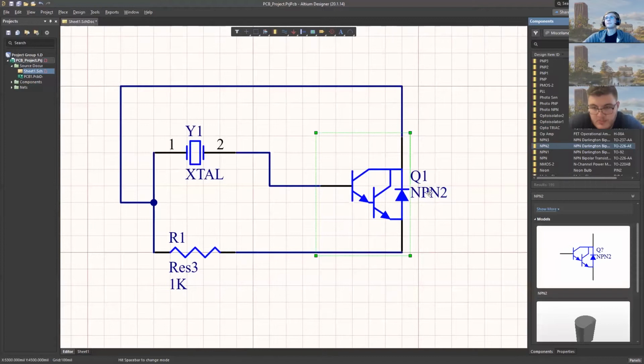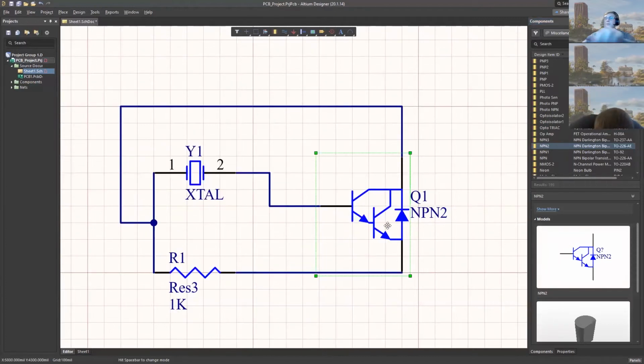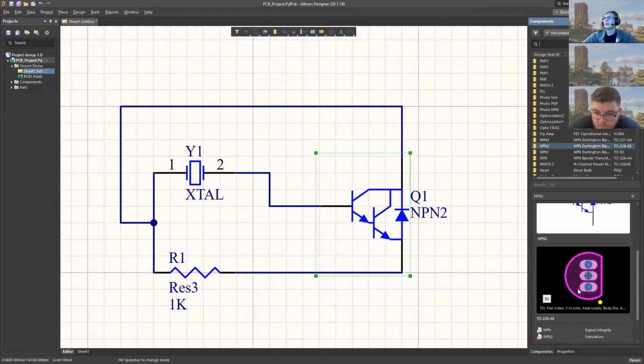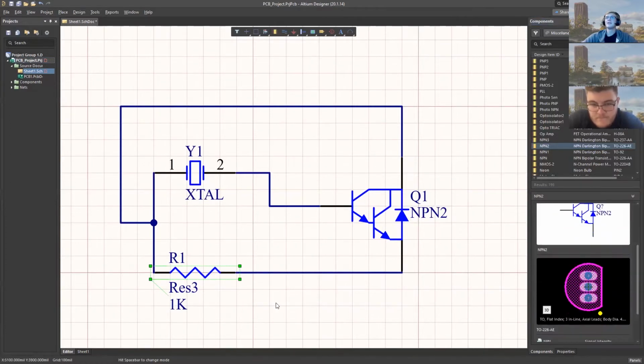So really quick, what a footprint is. Okay, here's my schematic symbol, which everybody has seen before. But what does it mean in real life, right, when I go to make a PCB? And the answer is it's this little box down here. This is the physical space. These are real world measurements that were used to generate this. And when you hand this to a manufacturer, they're going to actually mill what's given here. So this is the real world representation, and all of my parts have this, which is essential because I can't connect the parts that I promised I would connect if they don't exist.